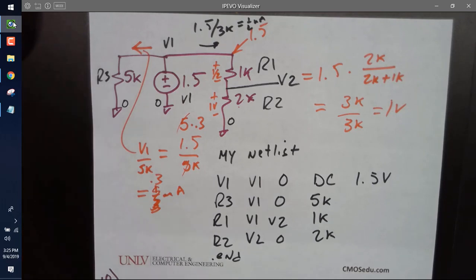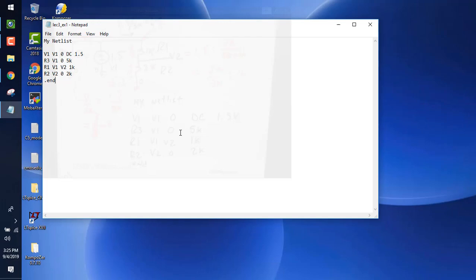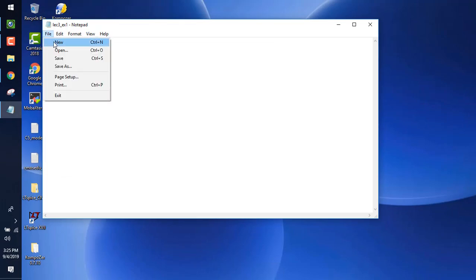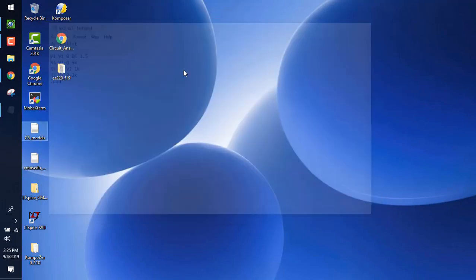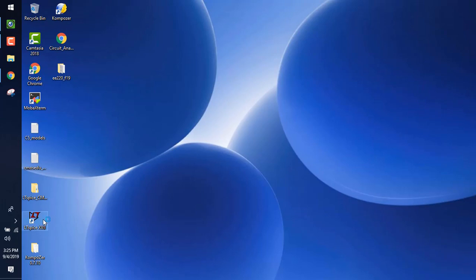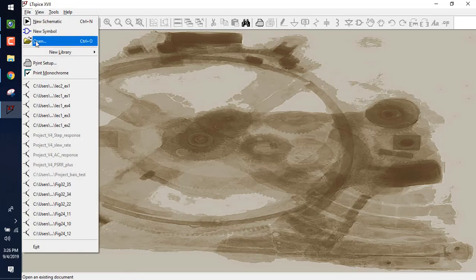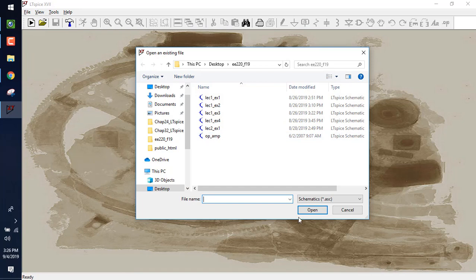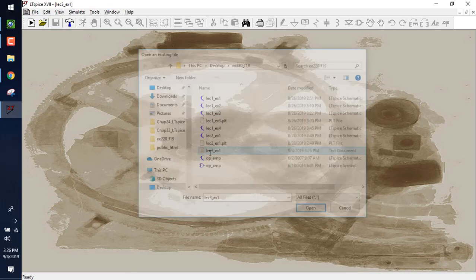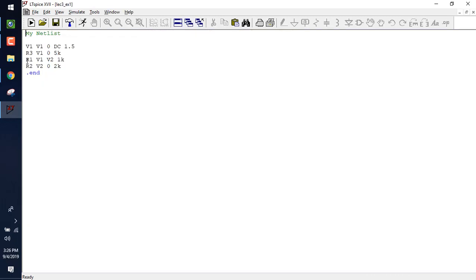That was hard. All right, so I hit File, Save, and then let's go back over here to LTSPICE and File, Open, and then let's go here and do All Files. Go grab my SPICE net list here, and hey, I can edit it directly in LTSPICE.